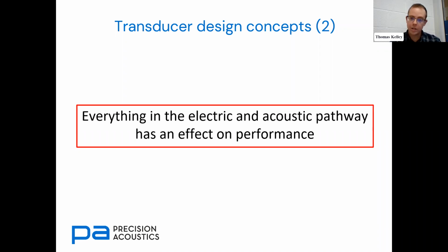So, you know, right from the initial drive signal, through all the cables, connections, through the transducer itself, the backing, the piezo, the matching, into the load medium, everything has an effect. And you must consider all of this together to really get the full picture of what your transducer is going to behave like.